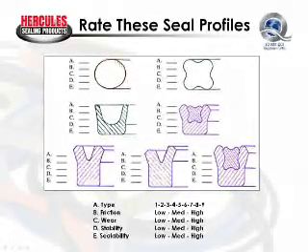So the round shape is the least stable of our seal shapes. So our stability on our O-ring seal is very low. So while we otherwise might think the sealability would be high, the round shape detracts from or reduces the performance capabilities of the O-ring to where it is no more than a medium performing seal.